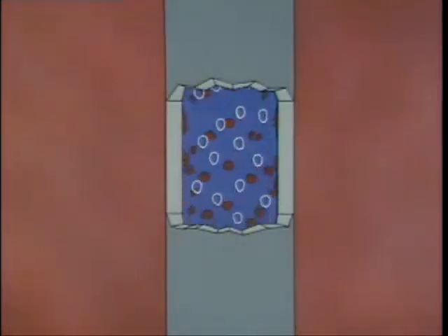Scale is the buildup of solid impurities on boiler components that contain water. The boiler's feed water supply may contain impurities. These impurities coat the surfaces, insulate them, and restrict their ability to transfer heat. If the surfaces can't transfer heat to the water, the tube can overheat and rupture.